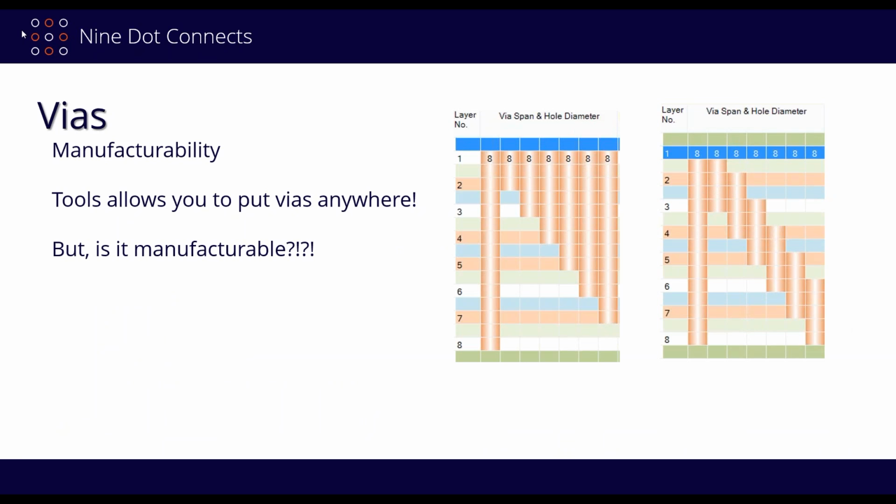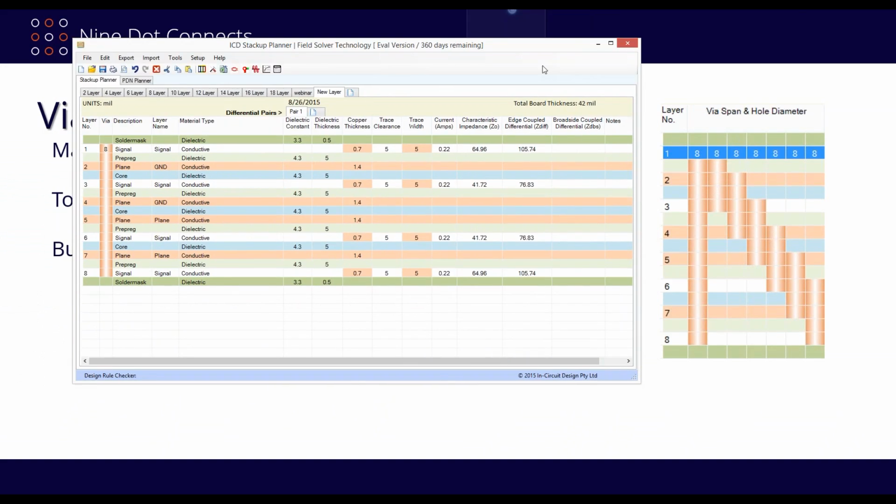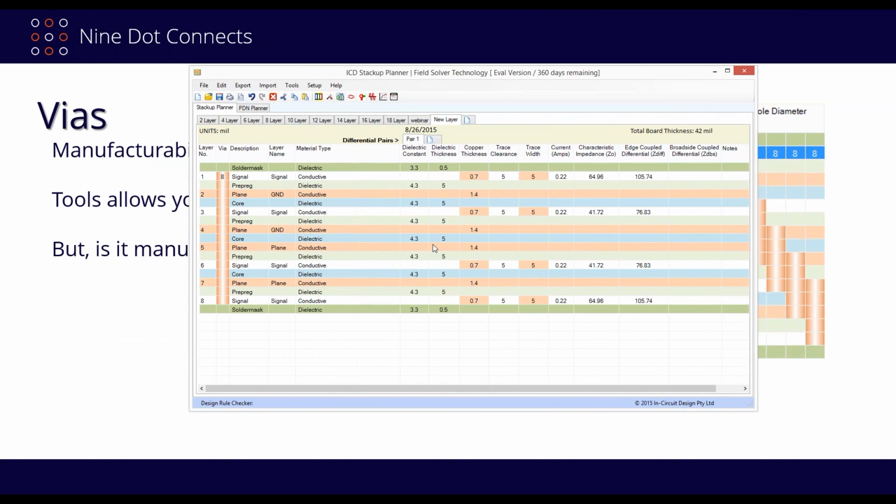The last example I'm going to give you is a real one, and going back to this one that we just made here, is just one strategy that you can use, one of many. It's not the only one, but one of many. And again, in a high-speed environment, for example, you're going to obviously have signals on the top, and you're going to have signals on the bottom. But what you want to do is kind of keep those things on the top to the top, and you can do that by saying, okay, look, I can do some routing on the top layer, but I need a little bit of help because I got a lot of components in the way. So I want to be able to drop things from layer 1 down to layer 3, and then possibly bring it back up again. Okay?